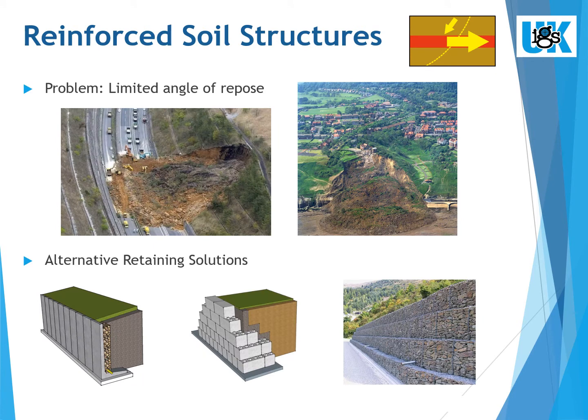The problem with soils is that they have a limited angle of repose related to the friction angle and cohesion of the material, which can lead to failures if a soil slope is oversteepened, overloaded, or the strength reduces due to groundwater changes.